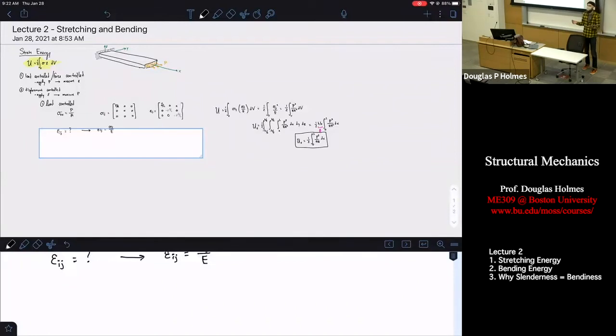We can do this again for displacement control. This is the form that I am more typically used to seeing in evaluating the behavior of structures. I think part of the reason is it's really easy to walk around and see how much an object is deformed, and you need some sort of tool like a scale or a load sensor to tell how much force you're applying. It's easy to mark and see, well, I know this thing used to be this long, now it's this long. So strain is often easier for us to observe in practice than load.